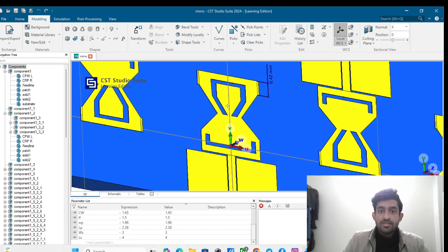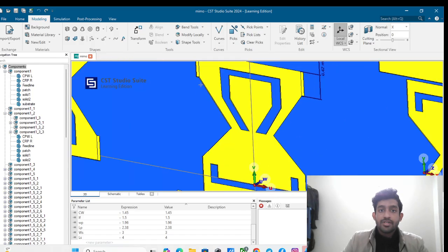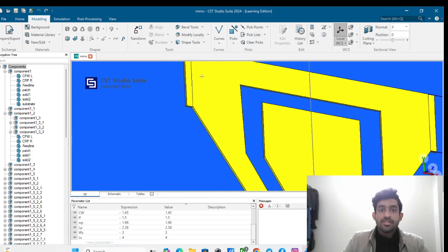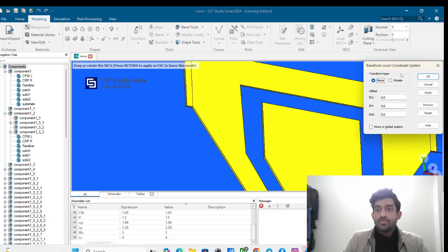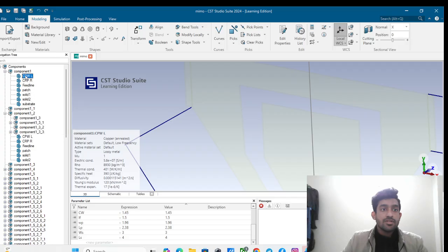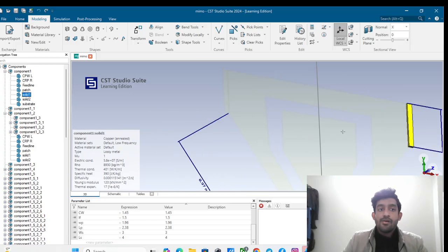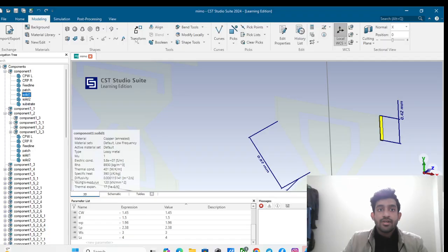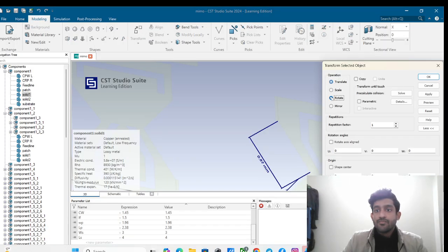After making this part, I have created this angular part, and if I make one part, I can copy and rotate it by using this transform part. Here this is not shown. I can show you, sir. After selecting one solid part, I can transform it: rotate, scale, translate, or mirror, and also increase the number of vectors.